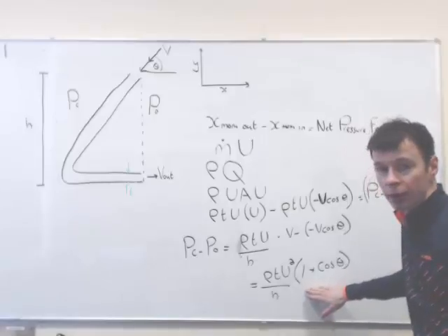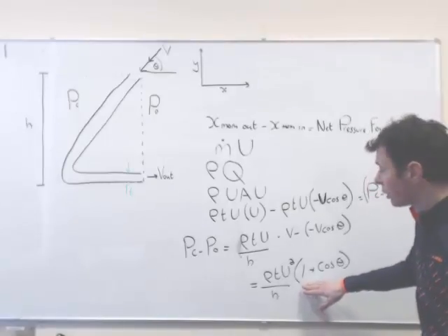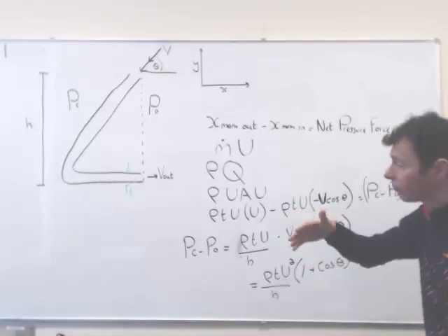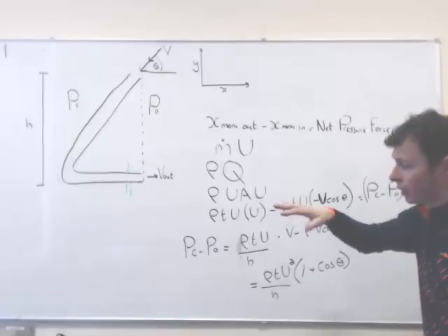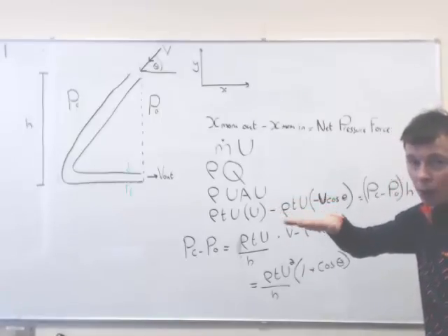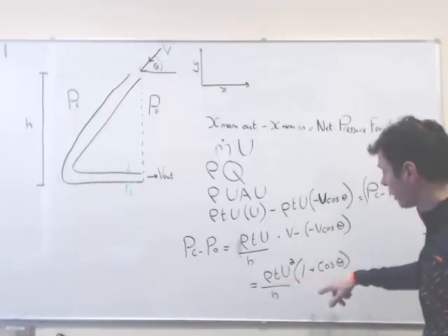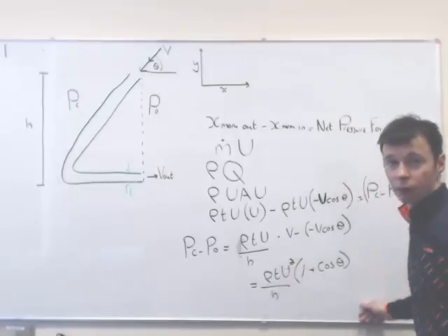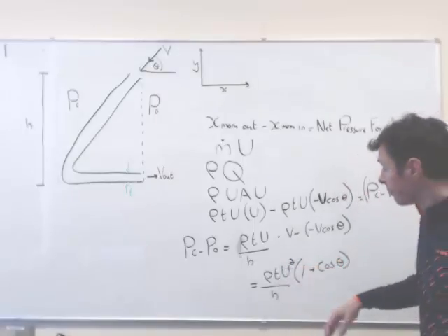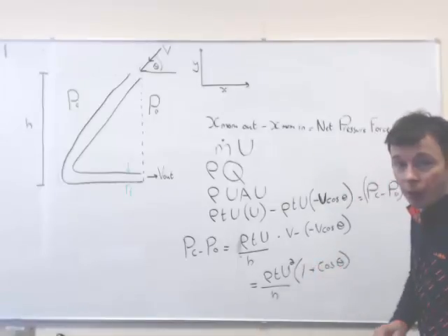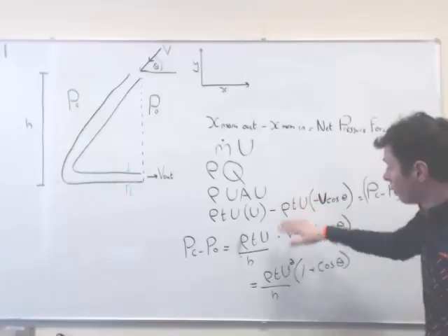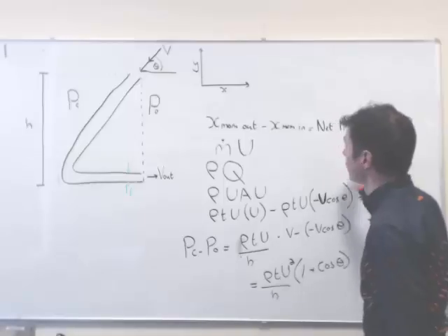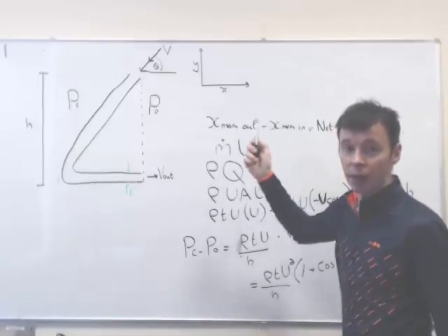And this equation you can then apply to the next question in this section concerning, I think, the outlet velocity and the mass flow rate to keep a hovercraft, so basically a platform with some mass hovering above the ground. So you can rearrange this equation, I think in the question, for u, for the velocity, whichever you prefer, to work out the velocity after you've done a basic force balance. So that's the basic answer to the question. Again, study the diagram carefully. You're given the equation, so it's a case of just working out the expressions for each, making sure that they're dimensionally equal.